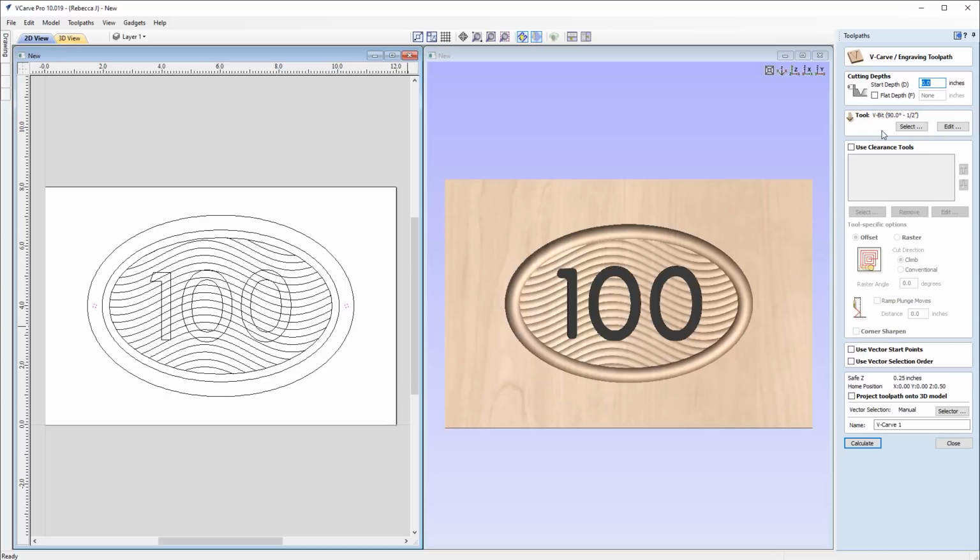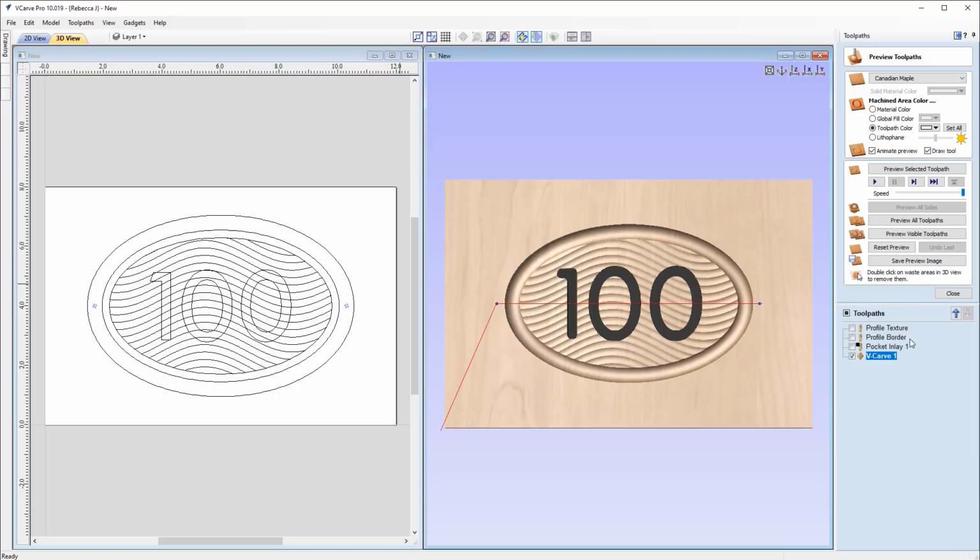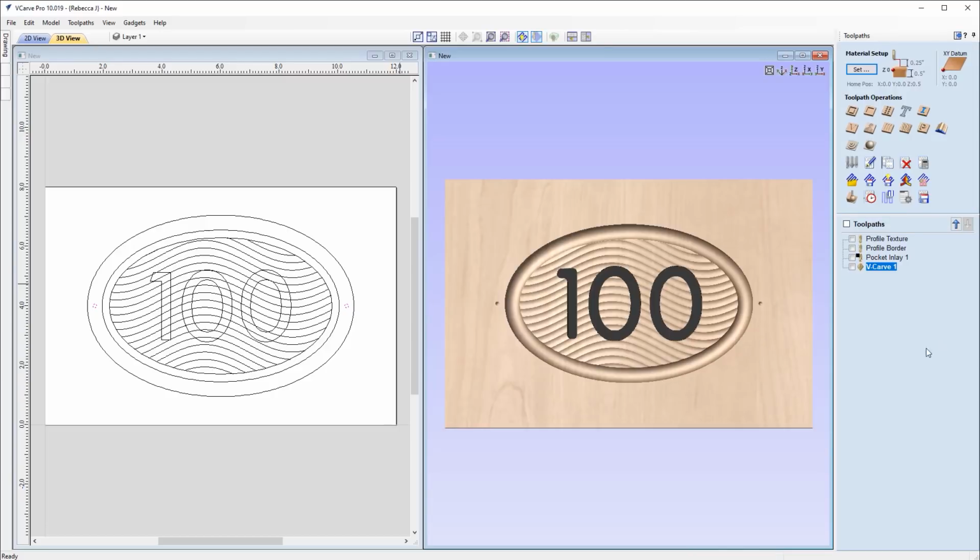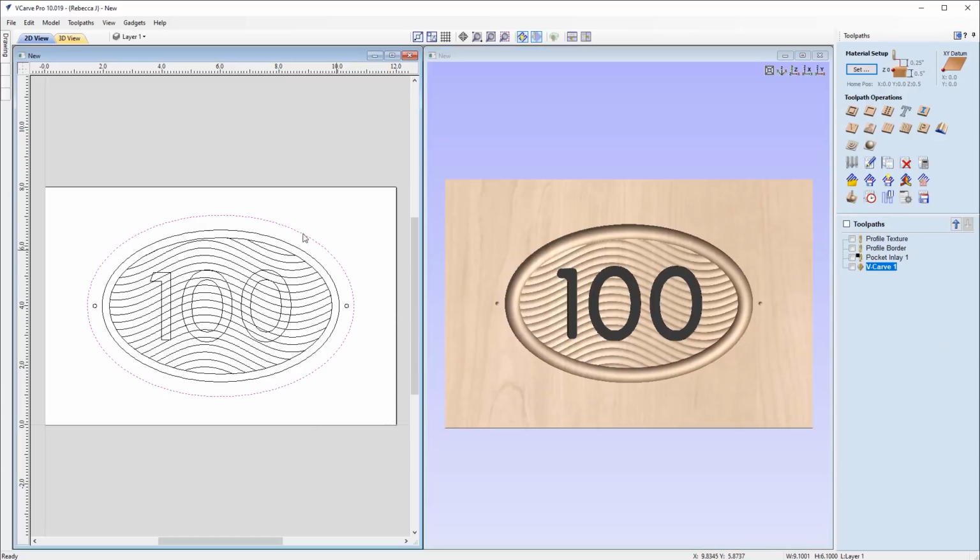All I want to do is just mark in holes as to where I know where I need to drill, where it's perfectly aligned in the center of our final cutout. So here we're just going to go the 90° 1/2 inch V-bit, calculate that, preview it, and you can see it just creates these 2 points for us, which is perfect. Okay, next up we can close out, and then we can just run a final cutout pass.